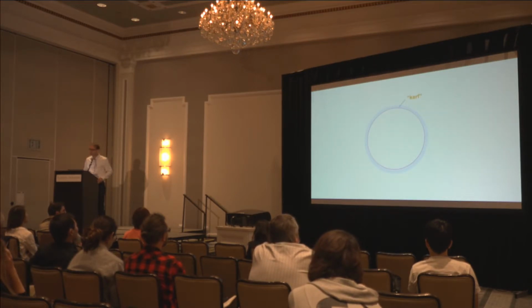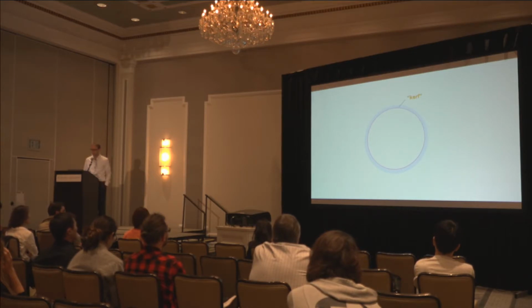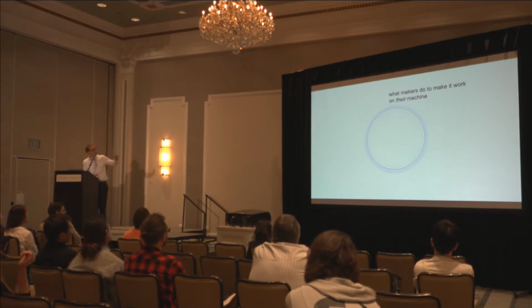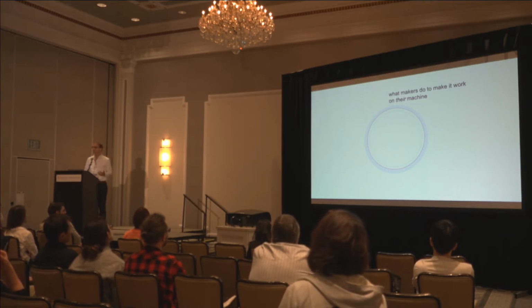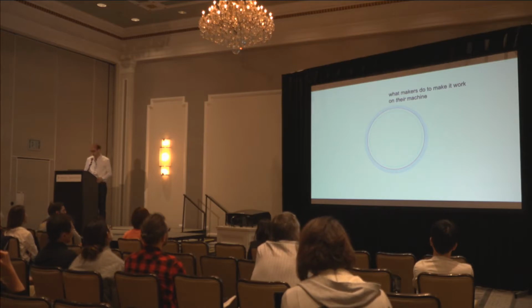Unfortunately, there is a concept called kerf, which is the amount of material that the laser removes when it's cutting. And that's the gray circle you see here. This is different for different laser cutters and for different configurations. So that amount of kerf there causes that button to not fit tightly in place anymore. The typical way to handle this is to erode the file. So like figure out in the model where kerf plays a role and then make all the adjustments to make sure that the cut, again, would now be fitting to exactly the same red line again.